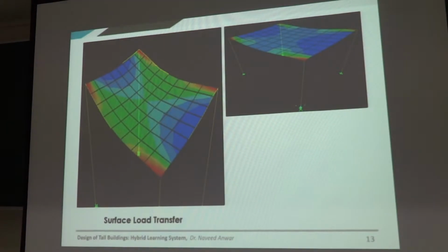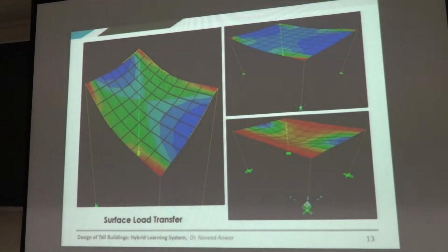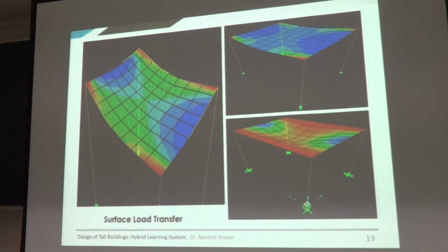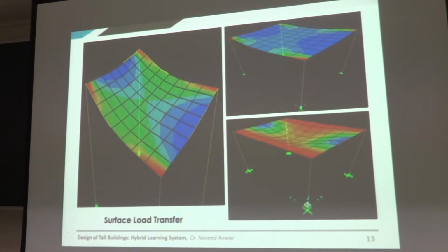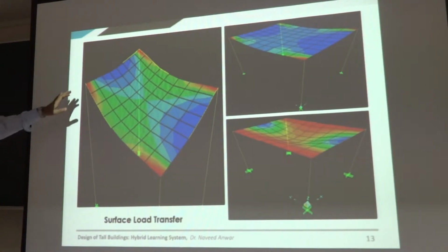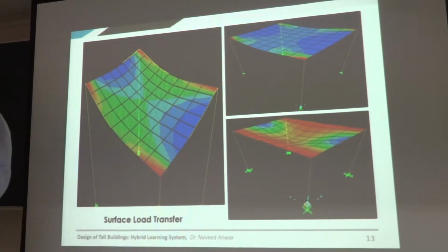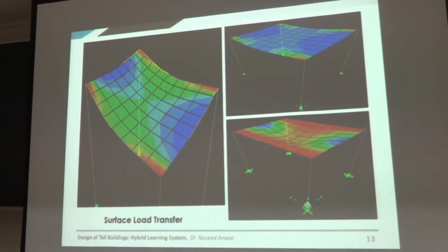You can see different views of the surface load transfer, and you can plot deformations, moments, and different kinds of moments from the analysis. Basically, what you need to see is that we have to mesh that slab into plate or shell, not membrane, right? So remember that for gravity load transfer, you need to do at least plate. We do shell because we also sometimes have in-plane forces.